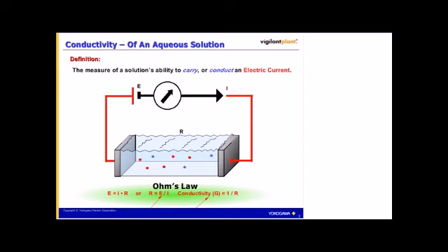There are two basic approaches for measuring conductivity that are determined by the type of sensor used. There's contacting and inductive, or non-contacting, which also is referred to as toroidal or electrodeless. The contacting method, as the name implies, uses a sensor with 2 or 4 metal or graphite electrodes which are actually in contact with the solution. It is represented by 2 plates on either side of the solution in this diagram.